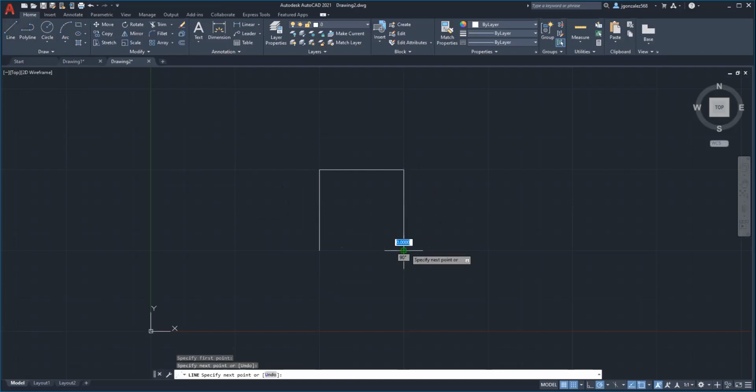Now you could just form everything at once if you want to. Not a big deal. Using the line command. But if I undo that, it removes the entire thing that I did at once. See how I connected 2 lines in one moment at one time? So the undo removed both of them. So sometimes when you're doing complex stuff, you might want to do a little piece at a time, depending on what you're doing, just in case you don't want to erase everything, right? It's kind of like a better save point, I guess. Anyway, let's remove all this and let's get to an actual example.